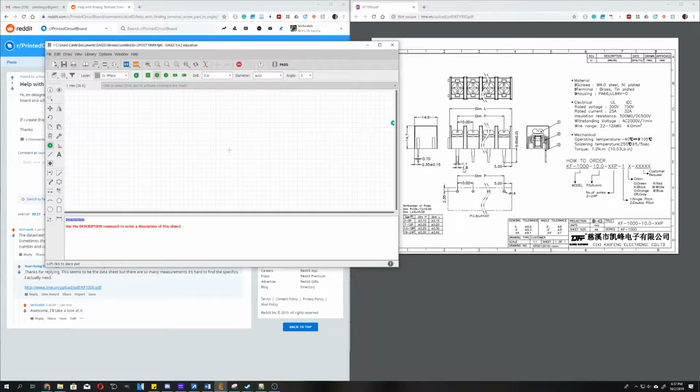So the drill, as we said, if this is 1.8, we want 100 microns on both sides of it. That would be 2 millimeters. So we'll set our drill, which is the hole in the middle, to 2. And then our diameter, we want that to be pretty large. So if we're talking our pitch from here to here is 10 millimeters, that means that a radius of 5 would completely bump up against each other. So let's say maybe a radius of 4. That'll give us 2 millimeter gap between the pads so that you don't bridge them when you're soldering. So that should be plenty for that. And so that comes out, if it's a radius of 4, that's a diameter of 8. And there we go. Let's go ahead and place down that first one.